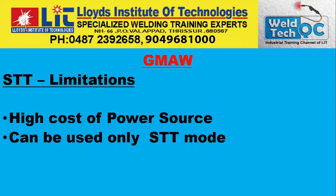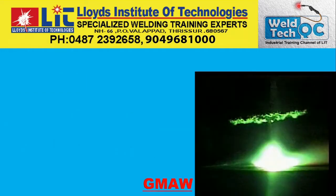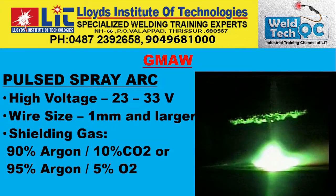We'll discuss pulse spray transfer now, the other modified version, which needs higher voltage ranging from 23 to 33 volts. Wire size will be 1 mm and larger, and shielding gas will be 90% argon plus 10% CO2, or you can go for 95% argon and 5% oxygen. And let us see how we can achieve a pulse spray arc and its advantages.